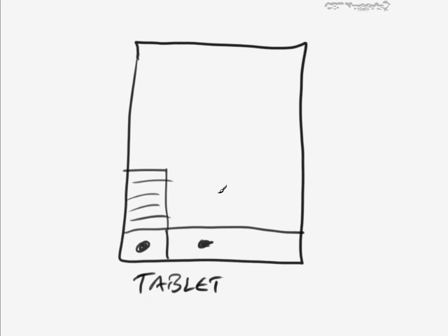Here's the key thing about troubleshooting these things. Normally when you first buy them and power them on, it should identify that you need to calibrate the touch screen. It'll put an X up here, for example, and say touch this, and then it'll put an X up here and say touch that. And then all the different corners, and then maybe in the middle, and different places. And it does that to vector where the user is going to touch things and how they touch things.